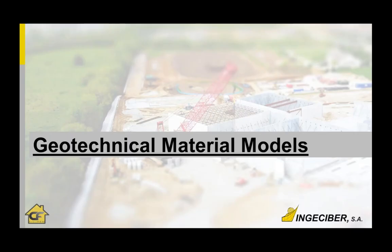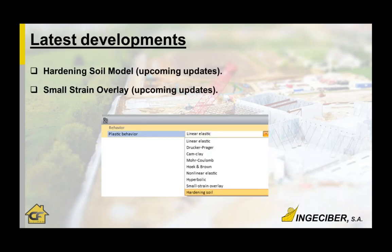Well, for the geotechnical material models, the latest developments are the hardening soil model, the very famous and popular hardening soil model, and also the small strain overlay one. You can see here the list of materials we have: linear elastic, Drucker-Prager, Mohr-Coulomb, Hoek-Brown for rocks, nonlinear elastic, hyperbolic. This is Duncan-Chang behavior, which is very similar to the hardening soil model results, and a small strain overlay.